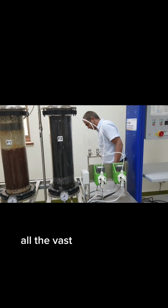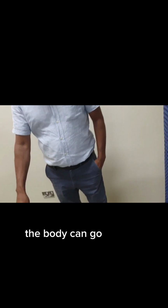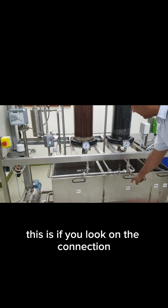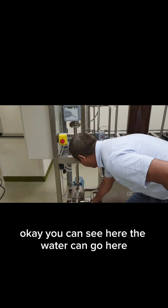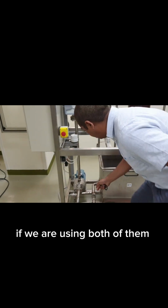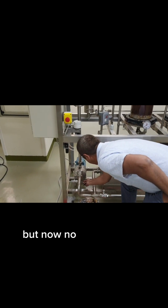We have to check that all the valves are closed. If one of the valves on the back side is open, the water can go outside from the pump. If you look at V6 and V18, they are all closed. These are already closed. So we have to fill this tank, and if you look at the connection, this is connected here. You can see here, the water can go here. If we close this one, the water cannot go in this one. But if we are using both of them, we have to open the valve V1. But now, no need to open the valve.